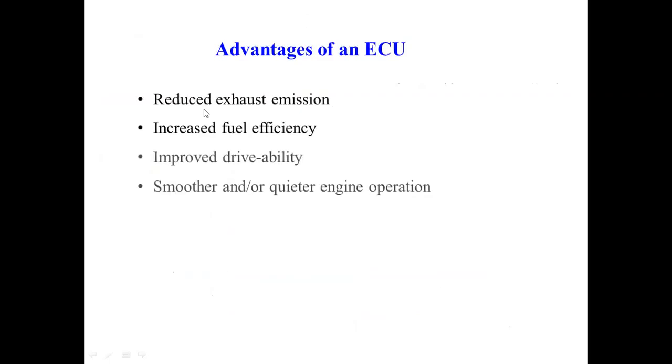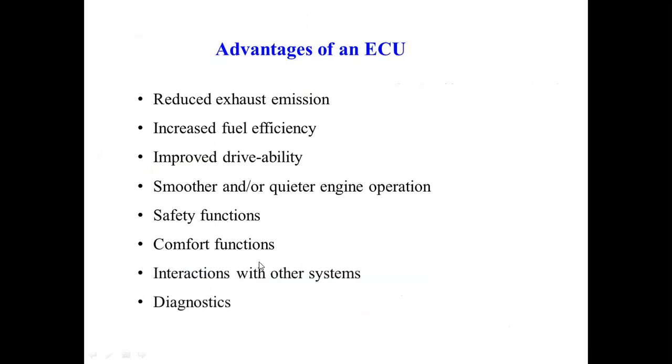Now what are the advantages of an ECU? The ECU reduces exhaust emission, increases fuel efficiency, improves drivability, gives smoother or quieter engine operation, it has safety functions, comfort functions, and interaction with other systems, and very important, we can have diagnostics.